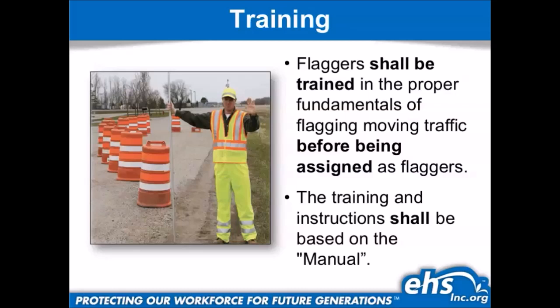So you want those hand signals to be consistent with the ones mentioned in the manual, which are stop, proceed, and slow down. And again, these guys have to be trained before being on the site, before working on the roadways. And training isn't, hey, here's your stop-slow paddle, it's pretty easy, get on the site. That's not the way it works. Again, if these guys don't know how to do their job and guide traffic safely through the site, if they do something wrong, everybody involved, especially the person who told them to be the flagger, can be held liable and responsible.